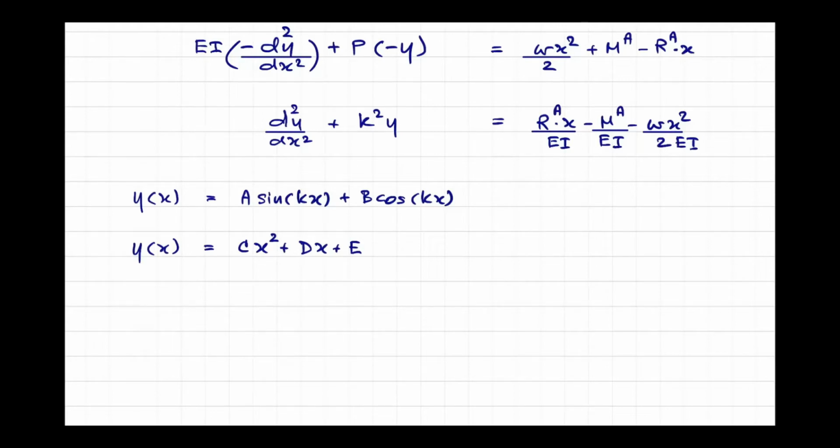Alright, fine. Is it possible to incorporate shear failure? Yes or no? That depends on the structural elements that you use. There are many kinds of structural elements in this program. Some are capable of exhibiting some difficult kinds of failure, like shear failure, crushing, etc. But some types of failure might not be incorporated. For example, bond slipping. What else? Gap opening, gap formation. Sometimes that depends on the construction detailing.